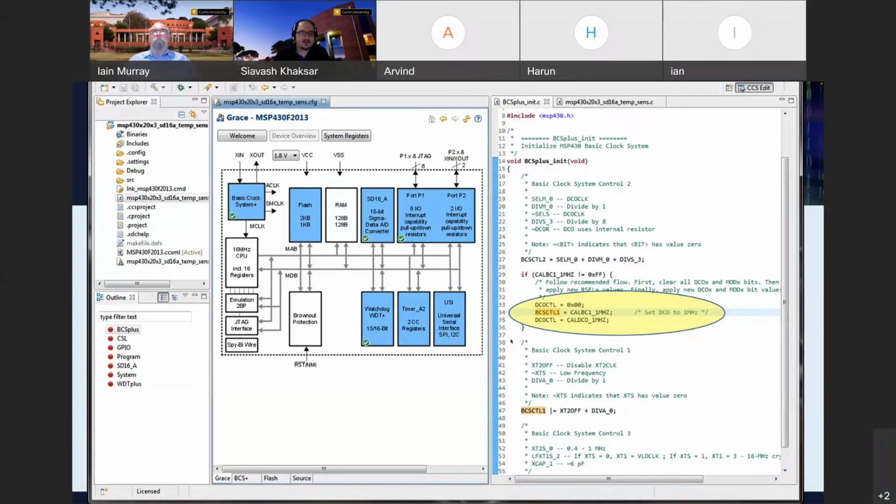So your source code will end up actually being larger when you implement it in an Arduino environment. There's a couple of other major benefits of using a more complex or more professional development environment. Number one is the ability to, as Savash mentioned, streamline or optimize your code. That's not just necessarily for speed, but in the IoT environment, it's very much about power usage and battery life. If you can slow the clocking of the processor down, you have major power savings.